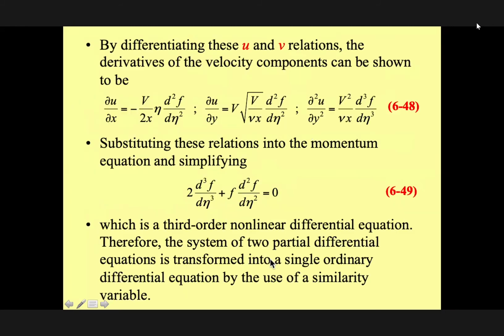Therefore, they end up solving this equation defined here. Now you have this form of equation, which is a third order nonlinear differential equation. The system of two partial equations is transformed into a single ordinary differential equation by use of the similarity, okay? They integrate these two equations together and find this one.